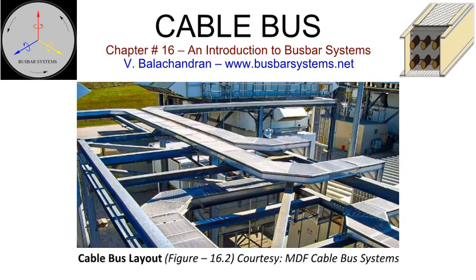Some of the key features of a cable bus are: Cable bus usually does not have a conductor joint between the connected equipment. However, a joint may be deliberately introduced for a tap-off connection. Cable bus connections are maintenance-free. Cables in a cable bus connection are immune to moisture and corrosive gases in the atmosphere. Consequently, anti-condensation heaters with associated wiring, thermostat or hygrostat for sensing and control, breathers, and drains are not needed. Cable bus also does not require hot air blowing for removal of moisture before commissioning or charging after a long period of disconnection.